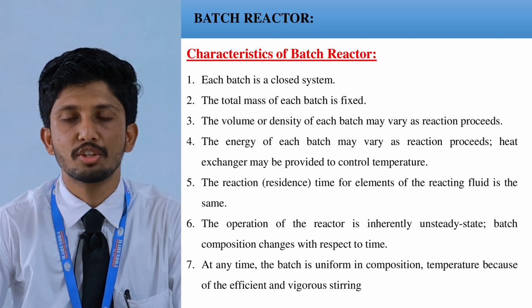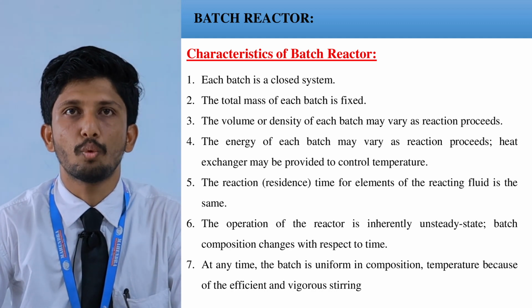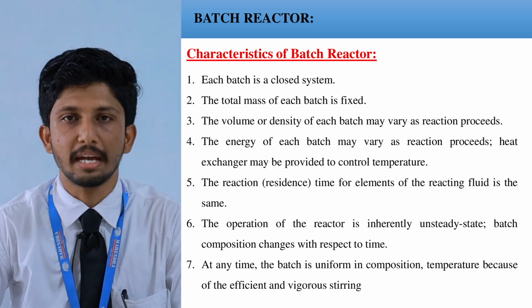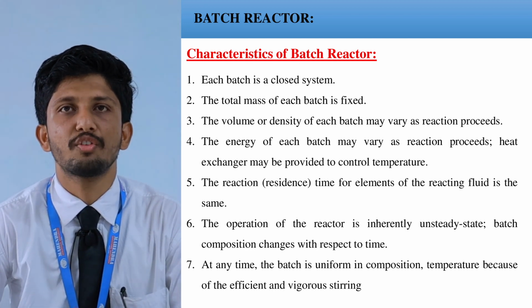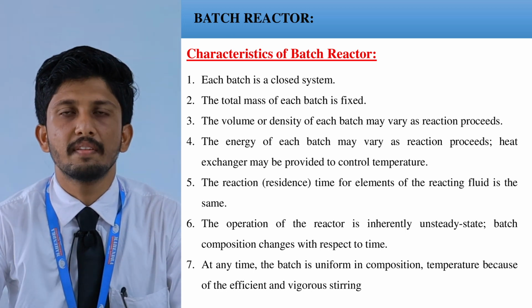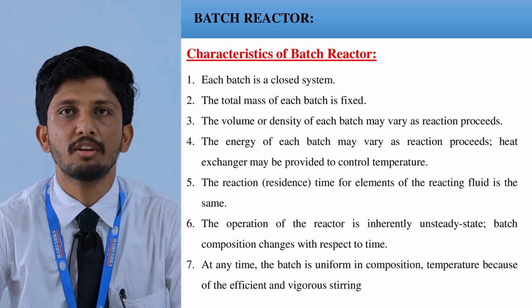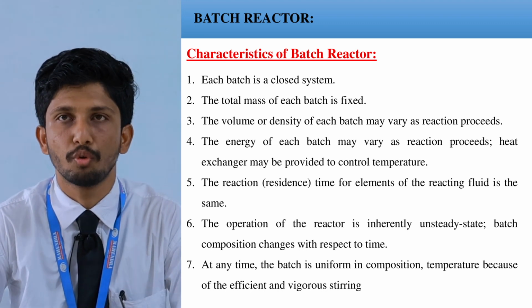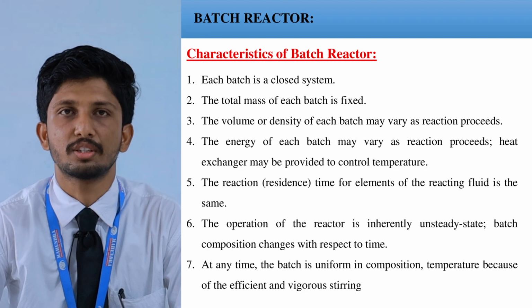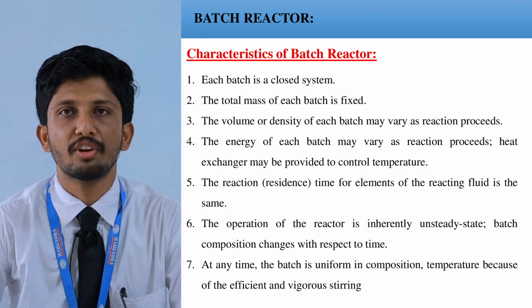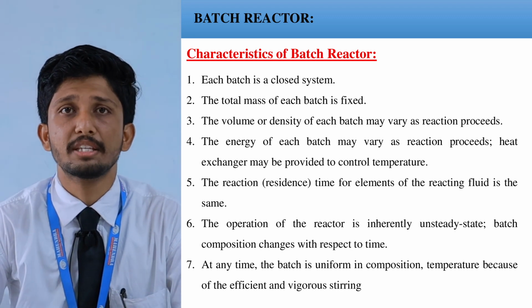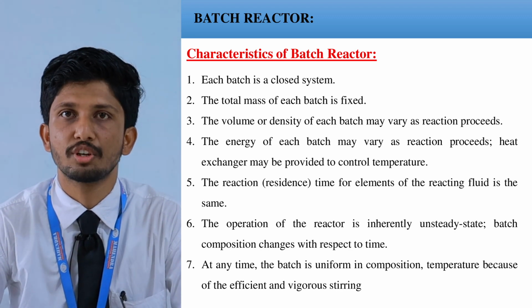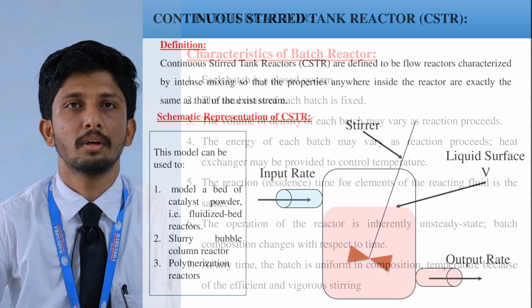Total mass of each batch is constant. Volume or density of each batch may vary with respect to reactions. The energy of every batch may vary with respect to reaction. The reaction time or residence time for elements of fluids is also constant. The operation of reactors is under unsteady state. Batch composition changes with respect to reaction time.